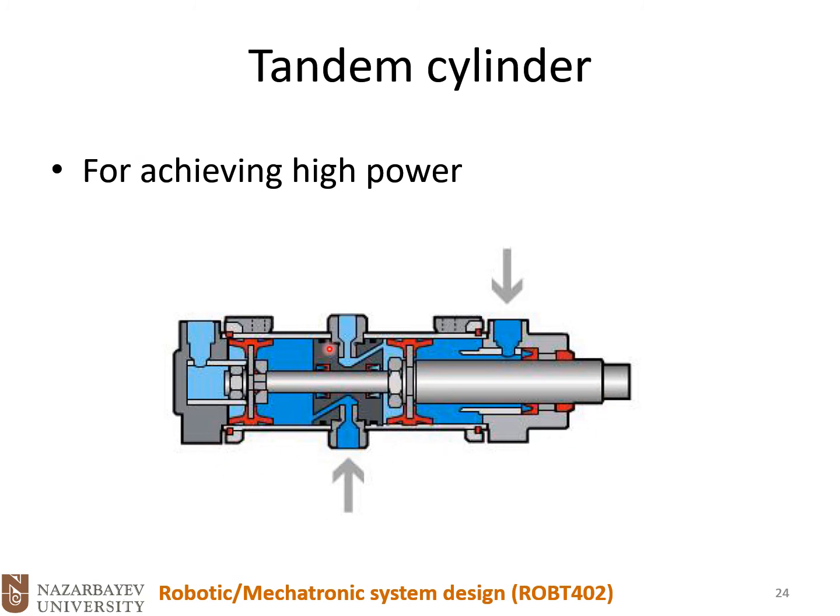So in this case, you could see it's very similar to multi-position cylinders, but the only difference is that this rod here is coupled or tandem to the second piston. Okay, so this piston is attached to this rod. So once you have high pressure on both chambers, the resultant forces will add up, and we could have a higher resultant force at the output.